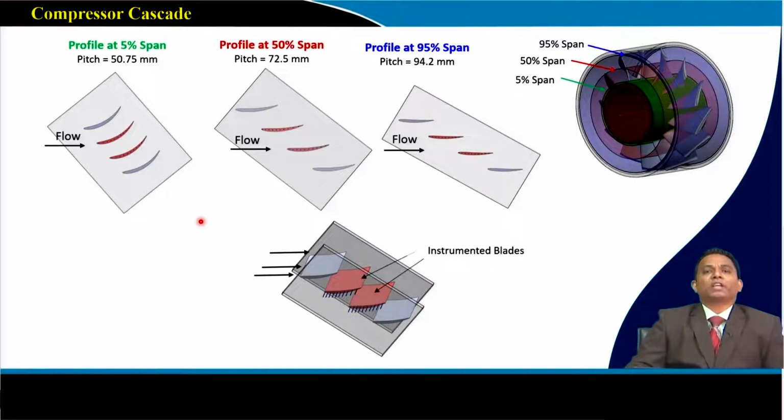Systematically, people did experimentation and built a bulk of data for particular kinds of aerofoils with different angle configurations, and they have a whole lot of data for all different kinds of aerofoils. As and when required, they recollect that data, and those aerofoils are incorporated in a particular blade for a particular engine development. That's the importance of the cascade and cascade data.